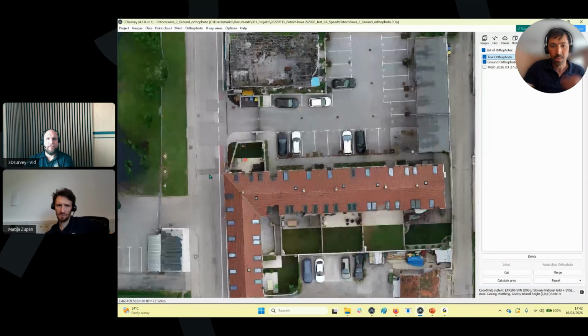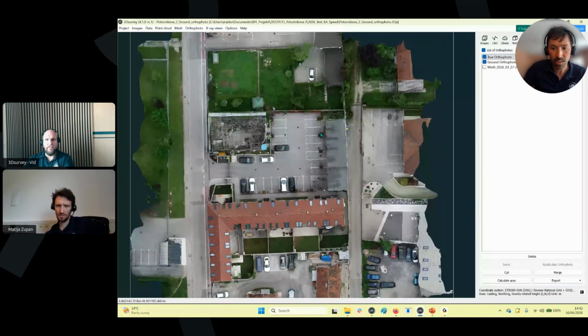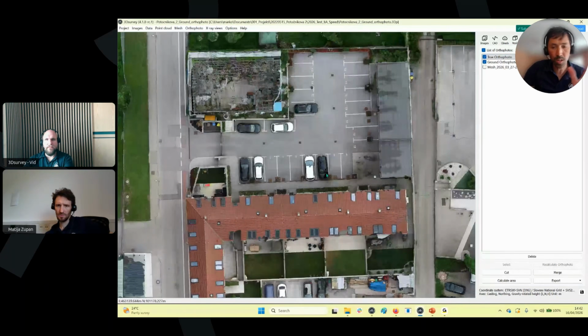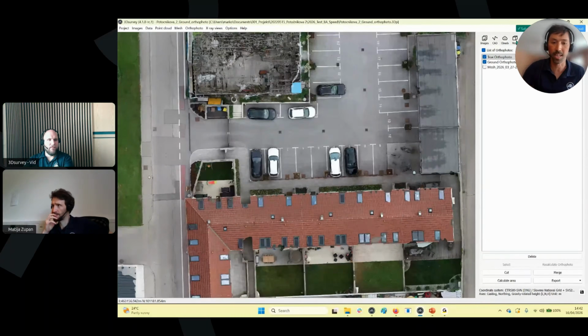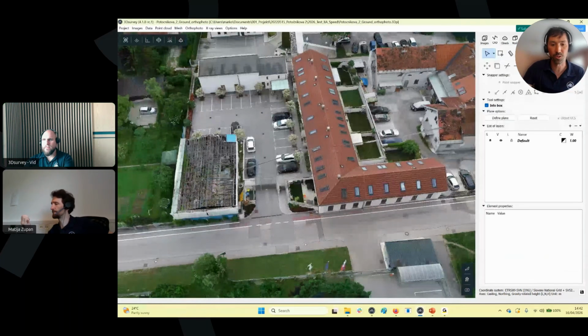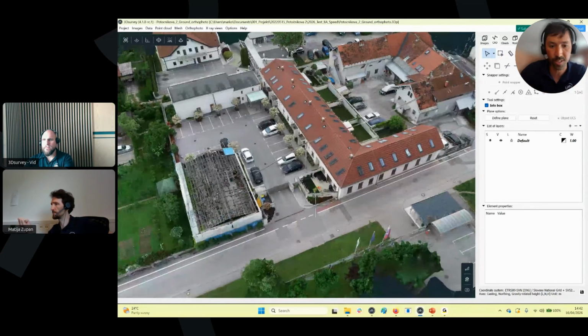Okay. Then maybe just an additional explanation of what you can do with extracting out here. One option is to export the orthophoto and draw something in AutoCAD or something like that. Or the second option is that you drape this orthophoto on a plane and finish your CAD data extraction in our CAD tab. Okay. If there are more requests, we can record a short video about this workaround and share it with you, of course, not a problem.